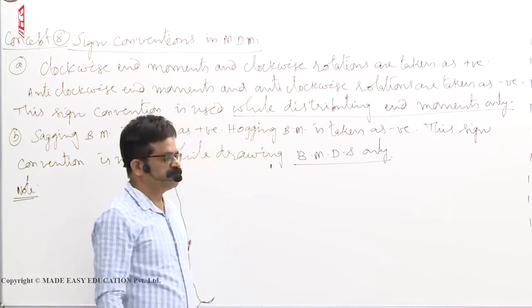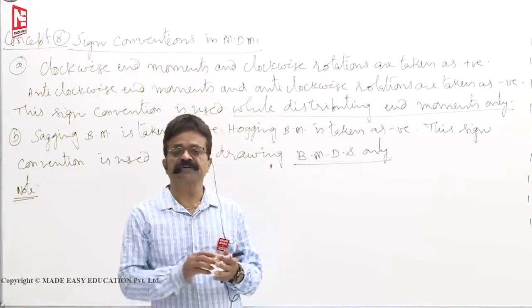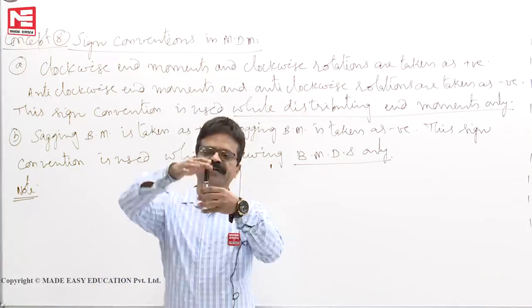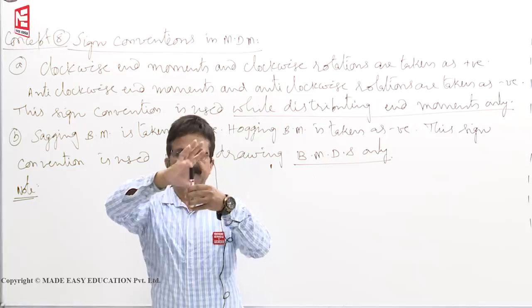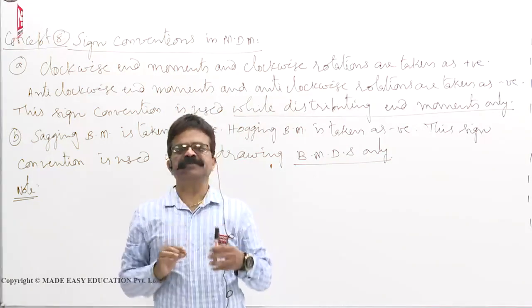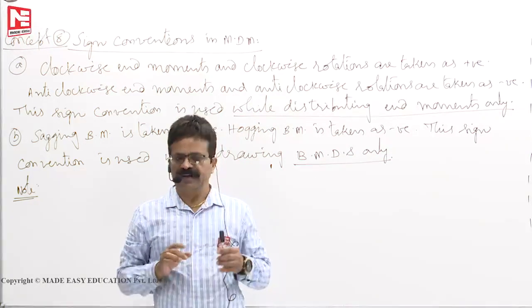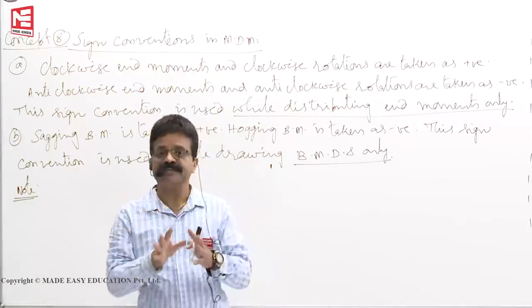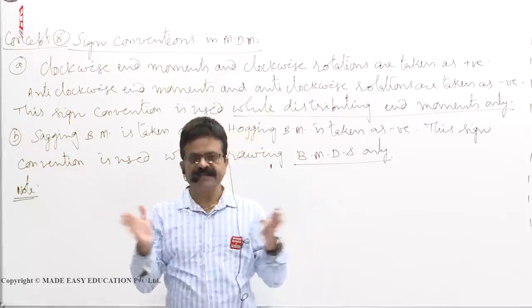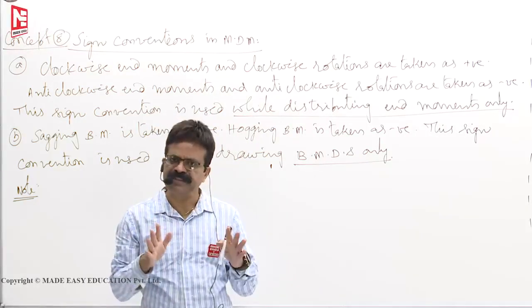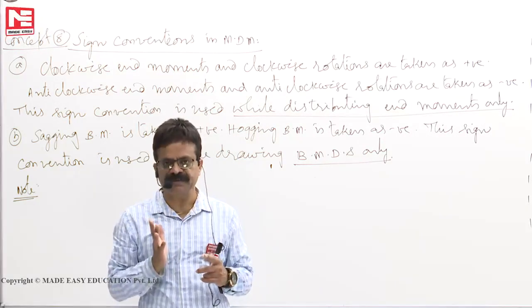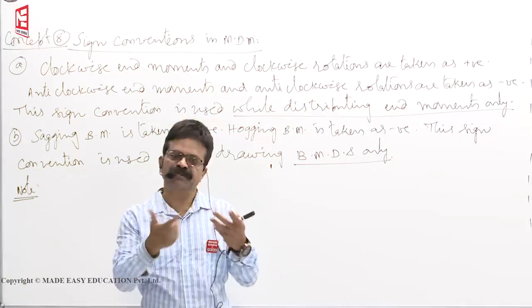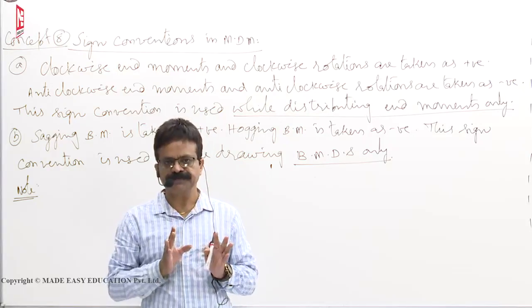So, effect of axial force means, in strength of materials you have studied, on this member if you apply a force P, let us say, then axial deformation is PL by AE. In frames or beams, where they are primarily subjected to bending moment, axial forces will sometimes be 0 or very little. So small is the axial force that the PL by AE value can be rounded up to 0.